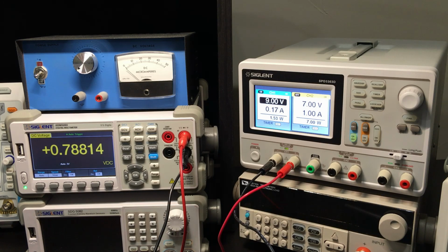In this example, I've hooked a potentiometer up in series with a diode, and we're measuring the voltage across the diode as we increase the current slowly from about 0.16 amps up to about 0.75 amps. Notice that although the voltage changes across the diode, it doesn't change by all that much given the huge range of current that we're changing. In fact, if this had been a resistor instead of a diode, that voltage drop would have increased significantly over that range.